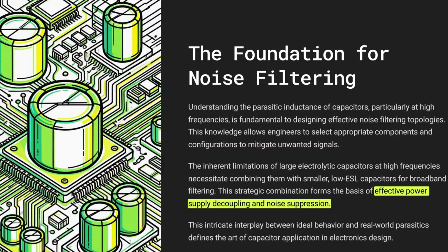So they're ideal for things needing repeated, quick bursts of energy, like in an electric vehicle's braking system. Absolutely, they have much higher power density. But the limitation is still energy density. They store way more than a regular capacitor, but they're still nowhere near a chemical battery for total energy storage. So for now, they're mainly for short duration, high power jobs. We've gone from a bulky lab rheostat to the future of energy storage.